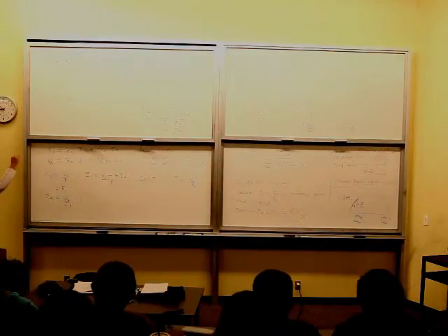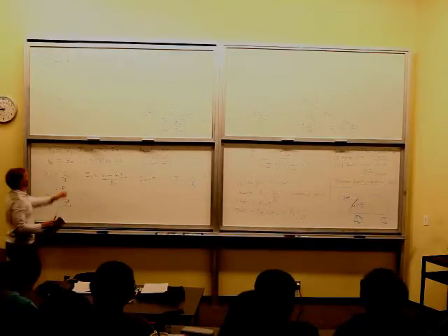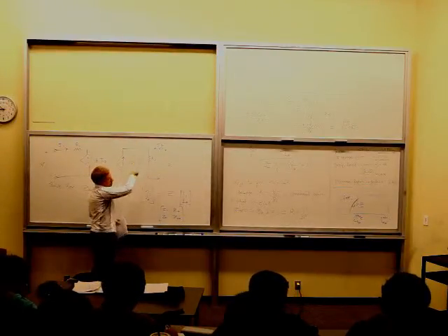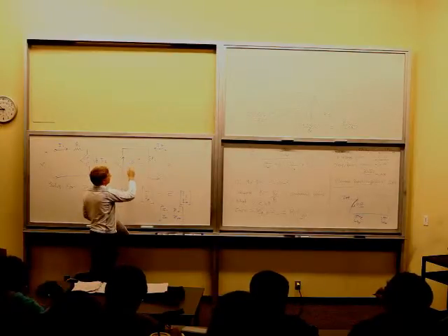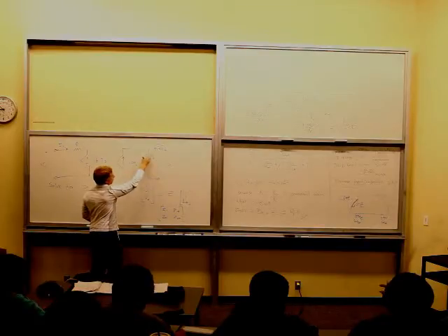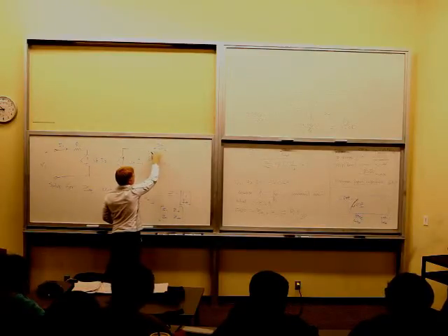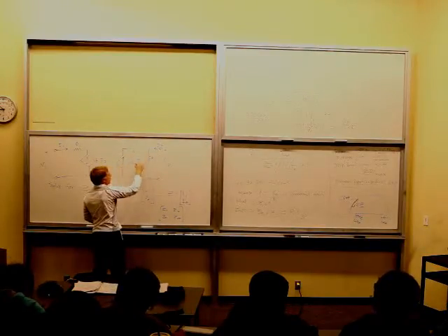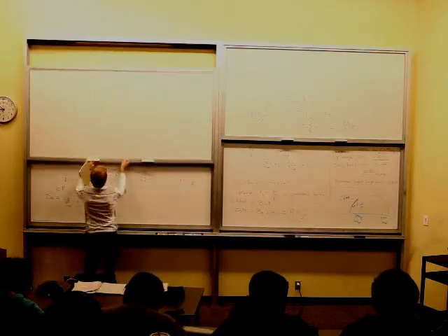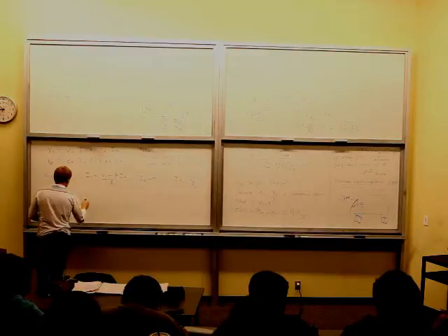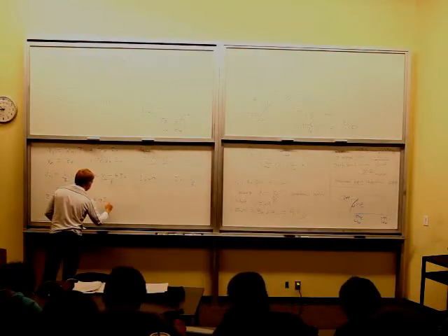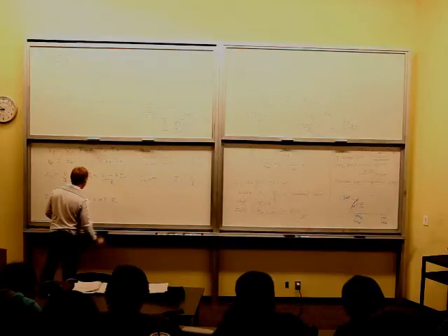So let's figure out what the voltage is through that little mesh up there. The voltage through here, if you think of, remember like that Thevenin and Norton stuff, is just going to be that current times that resistance gives you the voltage at this node. Because remember, there's no current going out there. We've set I2 equals 0, right? So it's going to be A I1 times R2. So we can say that V2 equals A I1 times R2.